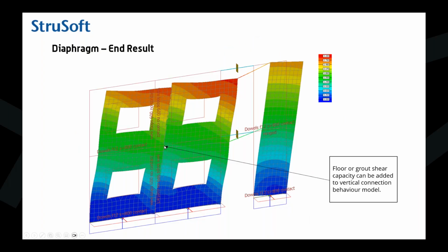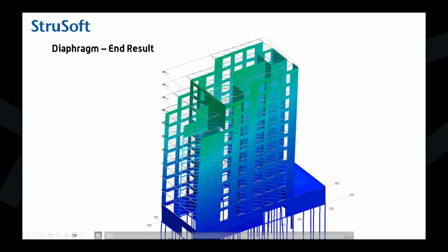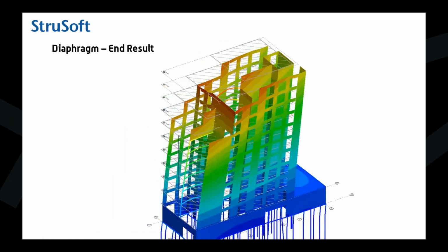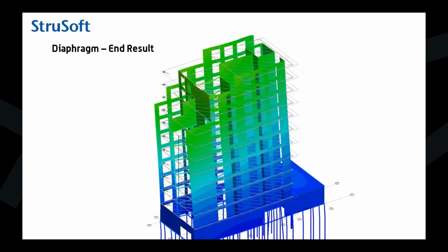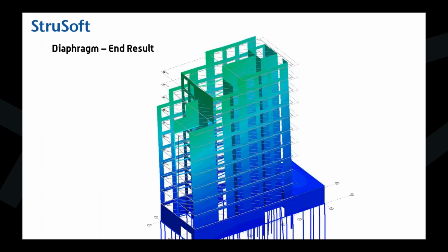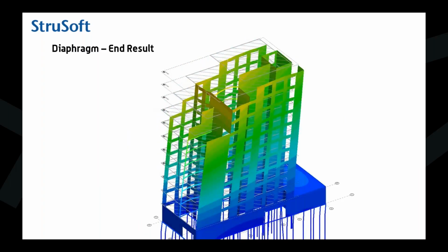And if you have succeeded with your model, it should look like this, because now they can slide. The diaphragm will bind those walls together in the horizontal direction. And if you have any bigger model, they will look something like this, bound together, so you don't need any floors. But of course, you can also add shell models in here, but then those shell models will become shear rigid, so they don't have any shear deformation anymore if they are inside of the diaphragm.